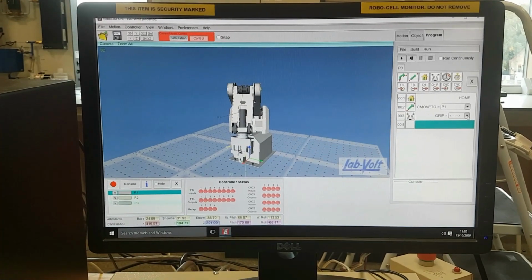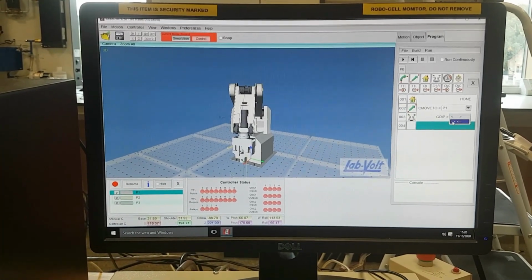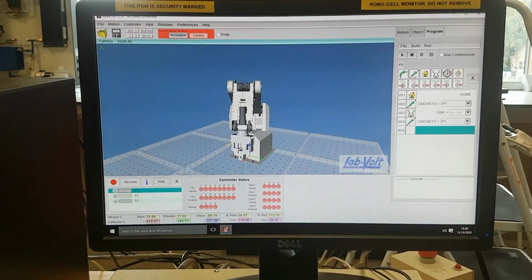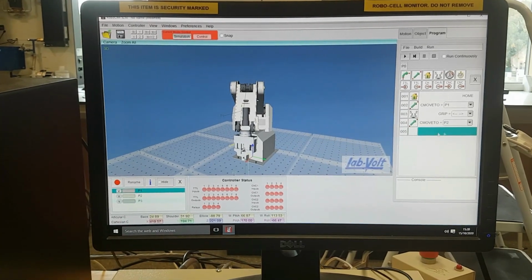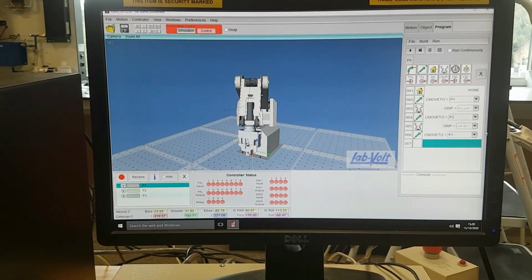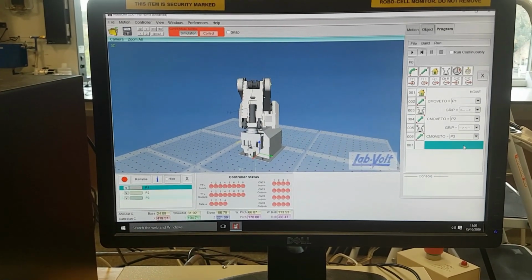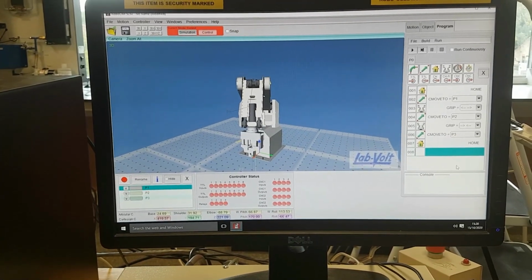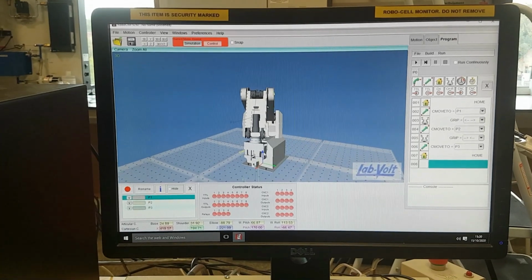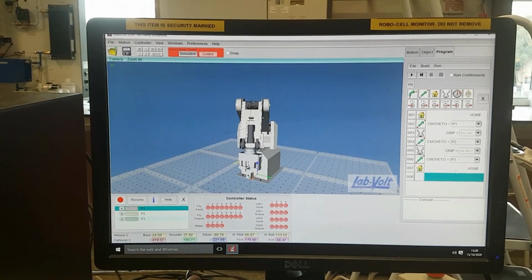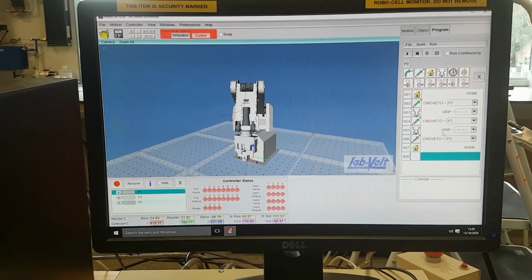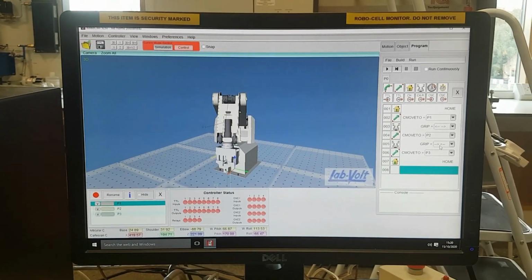If you see over here, you will see 2 options. Either the gripper will open or it will close. In the first instance, let's just open the gripper. Once we open the gripper, let's move it to point P2. At point P2, let's say that we close the gripper. Then let's say we move to point P3, and once it has reached point P3, let's home this. So everything that I did in my virtual workspace, points P1, P2 and P3, I have them all over here. In addition to those points, I have added the home positions, and the option of the gripper to open or close.